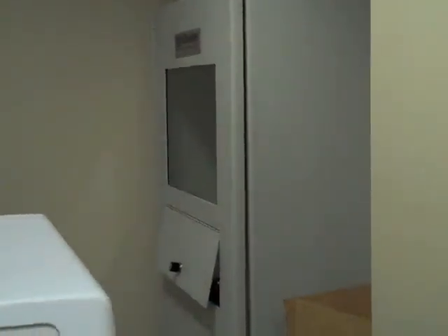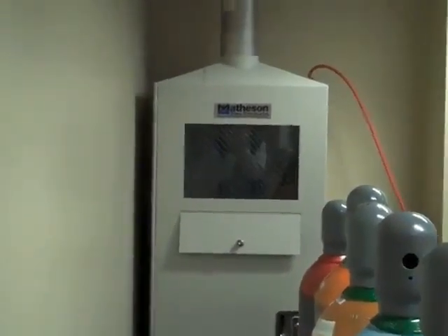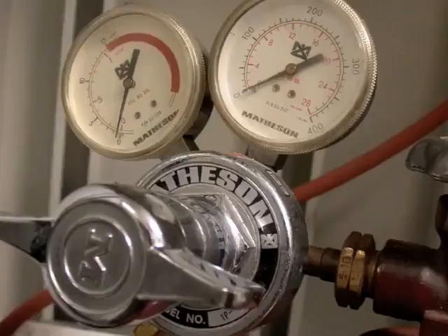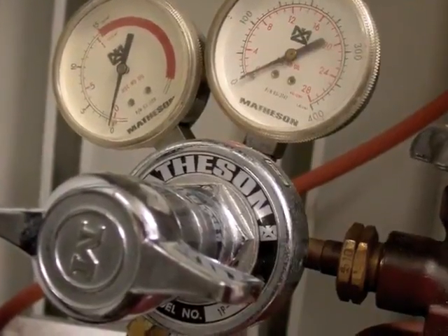The acetylene is housed in a safety closet behind the instrument. You need to turn on the tank. You can access the valve through the small trapdoor in the closet. Leave the control on the regulator itself alone. Instead, turn on the valve on the top of the tank. 1/2 turn counterclockwise should be sufficient to turn on the gas.